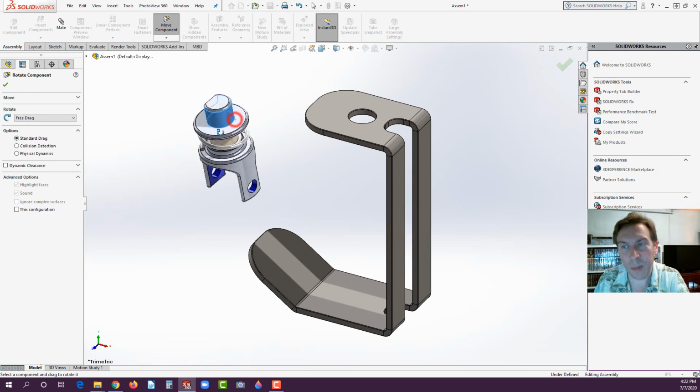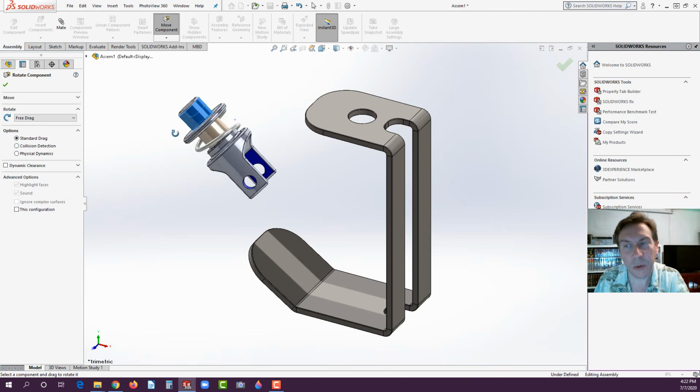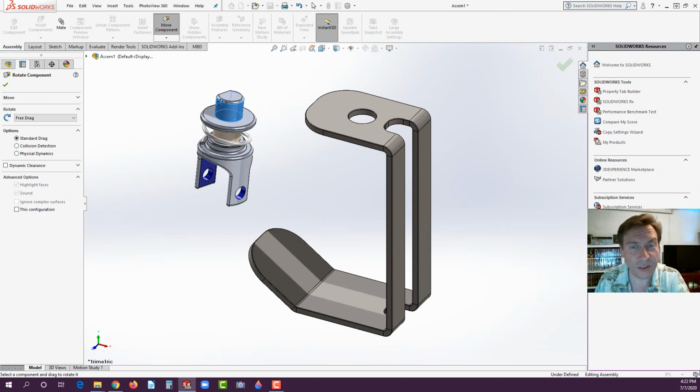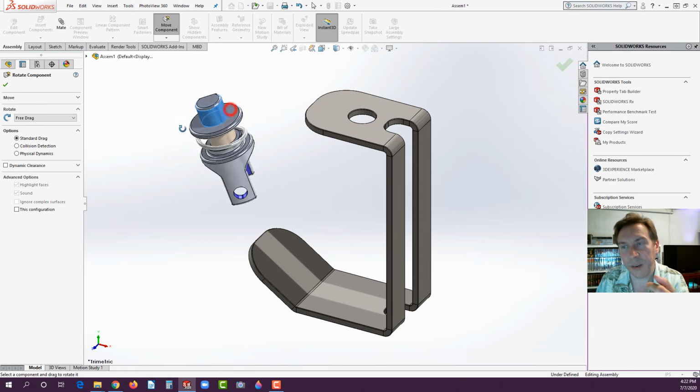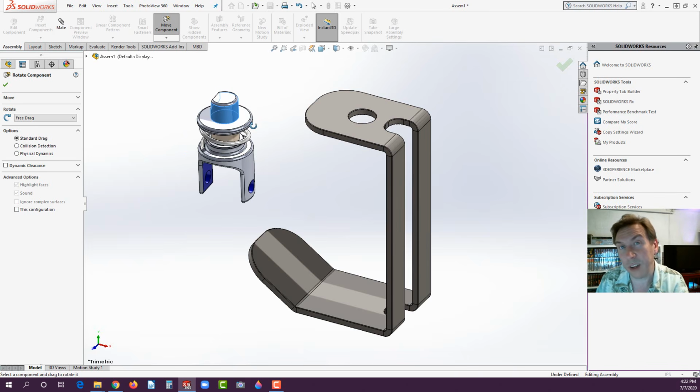And go ahead and grab the part, and you'll see now it will rotate. Now, right now it's just positioned to rotate around its centroid, the center of the model. So you could click and drag. And sometimes that's helpful to get it into position before you start mating, especially if it's somewhat of a complex mate you're applying. You don't necessarily always want the part going in upside down and then flipping it. And there are tools that help you to work through that. We're going to see those. Okay, but let's make sure it's pointing up like what you see here.